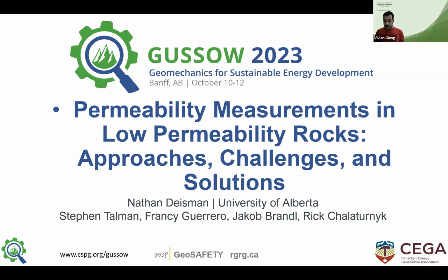Throughout the presentation, we will show results for a completed testing program on granite with permeabilities ranging from 1 to the power of negative 19 square meters to 1 to the power of negative 22 square meters, tested using isotropic configuration, stress up to 30 megapascal and 40 Celsius.